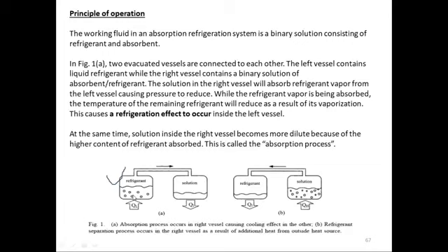Okay. Now, we want this process to keep on going, but it will not. It will go up to a certain point when the lithium bromide salt becomes saturated with the water, and then there will be no more process. Unless and until we can remove some more water from the solution, the process cannot go on. So we need a mechanism to reverse the process.